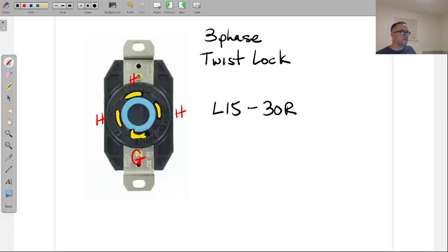And this one doesn't have the specs, the 31. It's not showing me the specs here. Yeah. I wanted to know if it was a 15. I guess I can zoom in on this one myself. You guys might not be able to see it, but I wanted to see the NEMA number on that one. Yeah, L15. I was right. Yeah, L15-30. And believe me, I didn't have this memorized. I just did it this morning and used it.